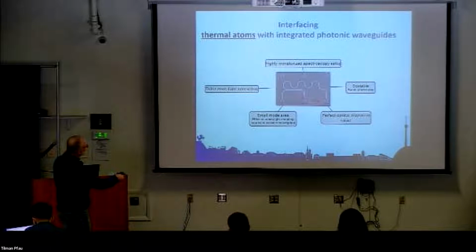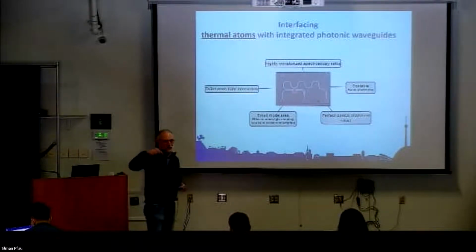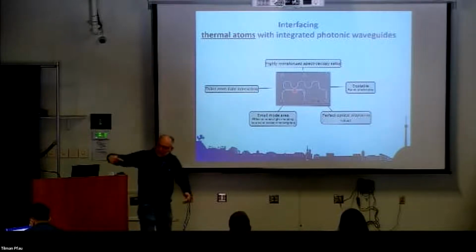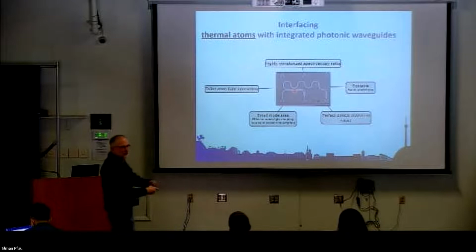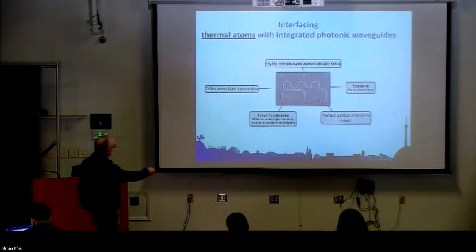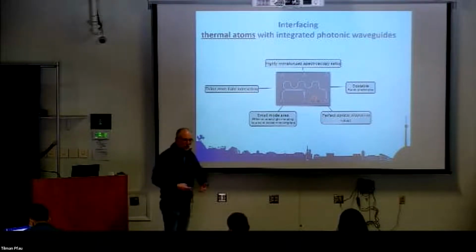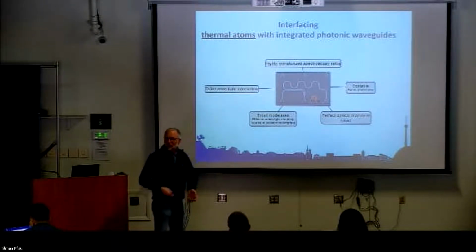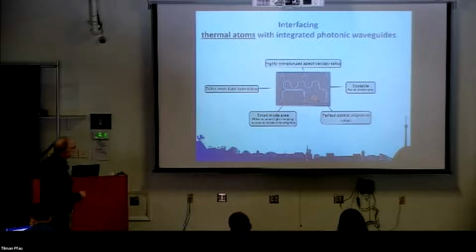And we are using so-called Bragg couplers here, which means that we are shining the light from the top, and then there is a grating that is diffracting the light into the guiding structure. So the light comes from the top into one of these couplers, moves around, and then exits here again. And so if you look at this chip from the top with a microscope objective, you see the light coming back out at one of these couplers at you.